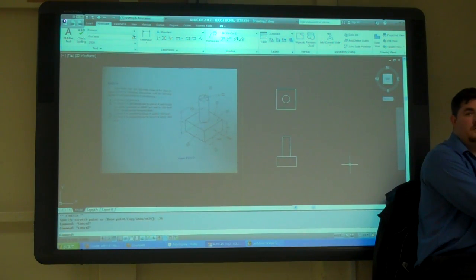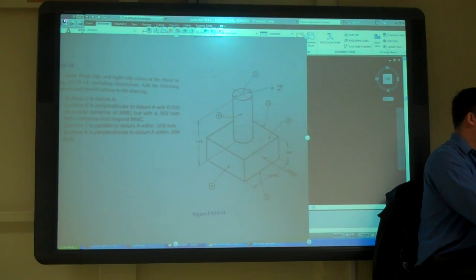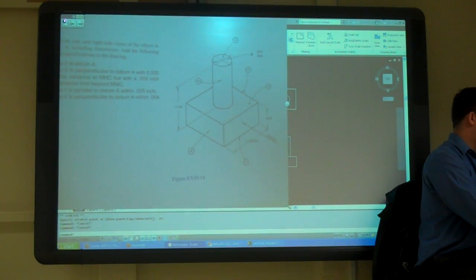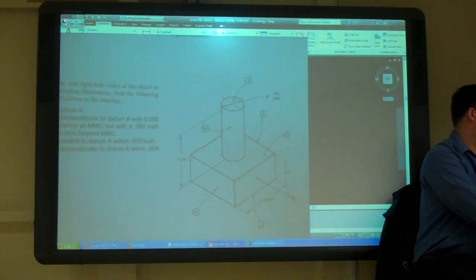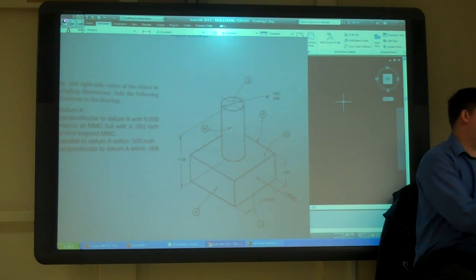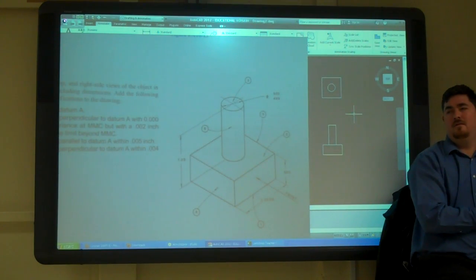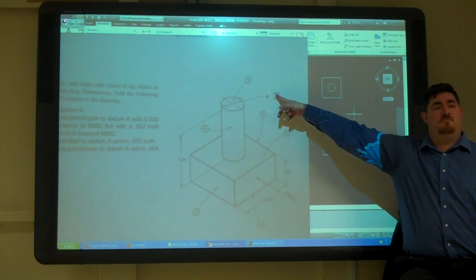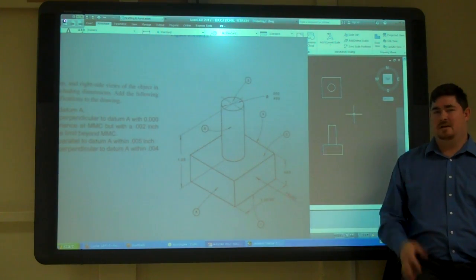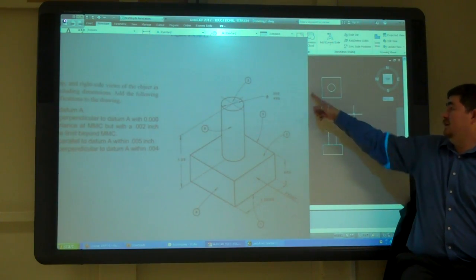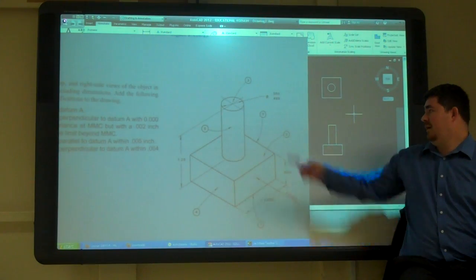There you go. On this part, it gave me a limits tolerance, right? 0.499 to 0.502. What size did I draw that circle? 0.5, right? It's in the middle there. That's our nominal dimension. It's a nice round number that's somewhere in there. I can dimension that and get this tolerance back out, right? So might as well do that.